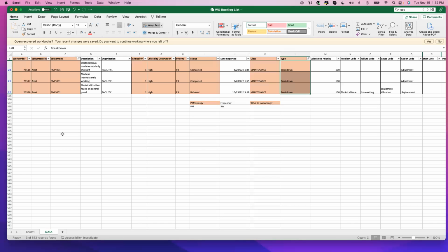Right. Another interesting point here is the cost code being equipment vibration, right? That could go back to a problem code not necessarily being an electrical issue, but something like a bad bearing or something like that. In that case, how do you assess it and understand that this may be an electrical issue on the surface, but on the root cause, this could be more on the mechanical side? How do you go about that?